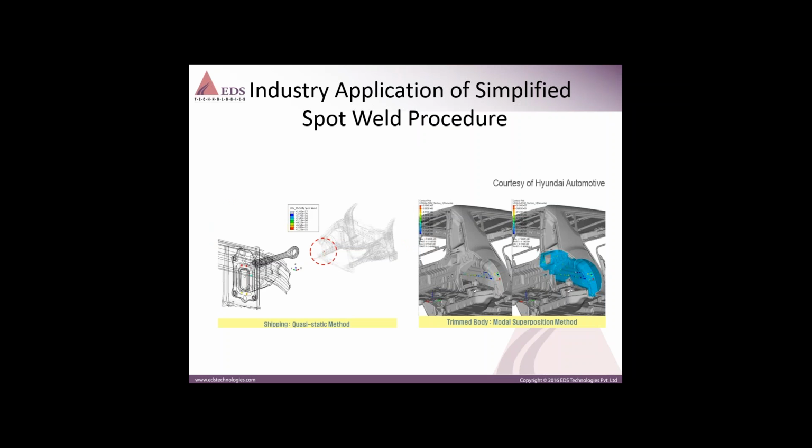One industry application example is here for the simplified spot weld procedure. This is courtesy of Hyundai Automotive, who are using this particular tool, and they are using a quasi-static method and the modal superposition method.